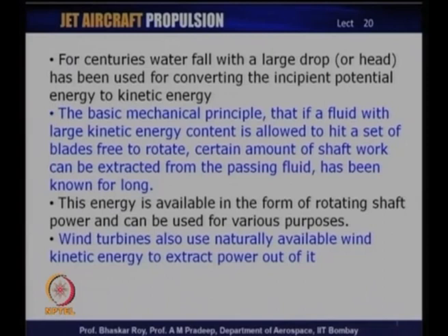Now, the concept of working of turbine is that if this fluid or gas with large kinetic energy is allowed to hit or impinge on a set of blades which are left free to rotate, then the blades would do work, they will rotate as they are free to rotate, and as a result of which certain amount of shaft work or shaft power can be extracted from this passing fluid or gas.